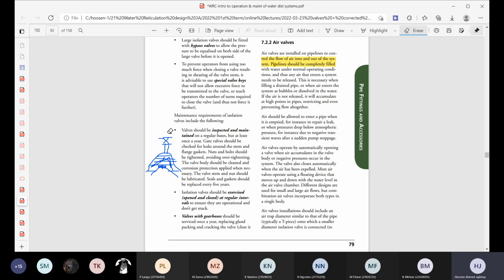How would air come in? The second way you can get air into a pipeline is that you may have dissolved air in the water. Just remember, where you have high pressure zones, if for some reason there were air bubbles in the pipeline, they can go into solution because of the high pressure. And as the pressure lowers, usually as you're reaching a high point on your pipeline, the head in the pipe will be less.